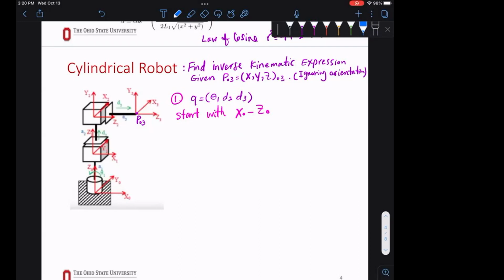That is our step 2. We are going to sketch what we see from the plane we chose. We need to go to as many planes as possible, so we have 3, to make sure that we see all of the joint variables. You will definitely see D2 independently. You will see D3, but if this joint moves, you will see a different length of that part, so that's not independent.